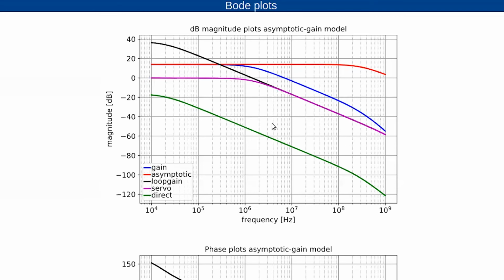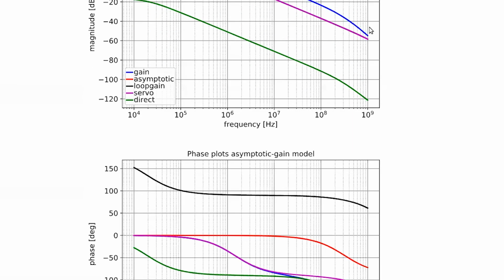The most important here is that you can plot all these functions, and the asymptotic gain is not a straight line, what we expect from the ideal gain, but there's an attenuator, you can say basically outside of the controller, although the parts are part of the controller, you can take it outside of the controller and see that the asymptotic gain is attenuated at high frequencies. And here, of course, all the phase plots belong to that.